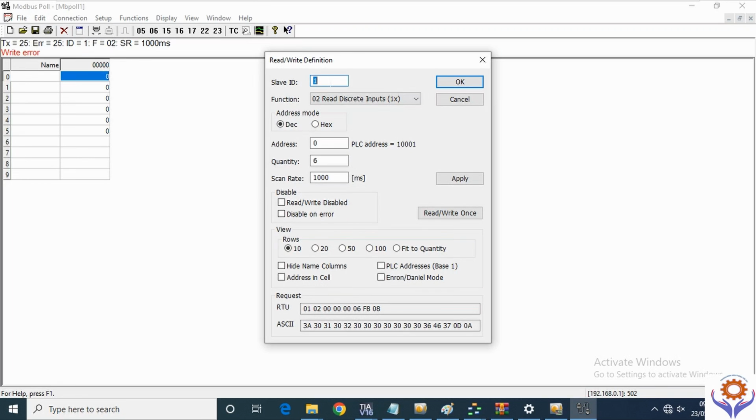See, here in the serial it is 1, but if you go to functions, yeah, it is currently read discrete inputs, and you can use here the Modbus registers from 0 to 60,000, and in the functions there is read coil, and I am planning to put the address as 1, and the quantity I'm planning to put up to 14.